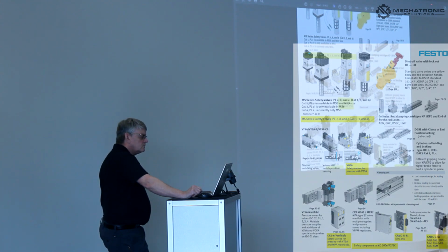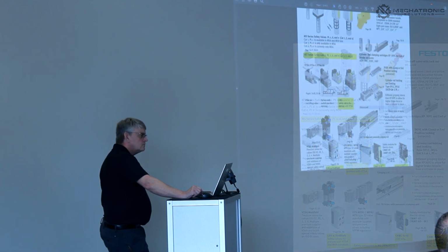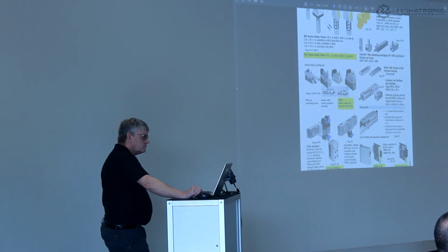Right, which alleviates a lot of, because the customers I hear from that don't want to dump air, it's just because they've got so many machines in their plant that they all dump air upon each stop, they are worried about whether the air can recover quick enough. Whereas you can limit that by just going to the most hazardous part of the application. Like I said, one of these blocks is specifically designed for pressing, and will actually make sure it tracks, so you can't get injured that way. Yeah, it's just that sometimes you don't want any movement at all after stop. Right. You don't want to traverse them back.